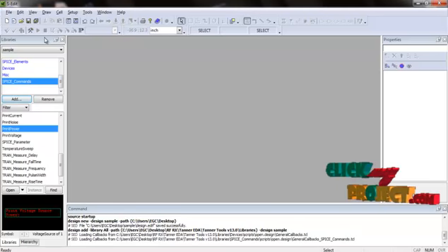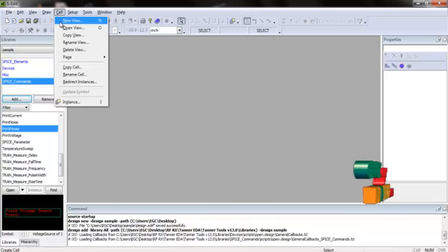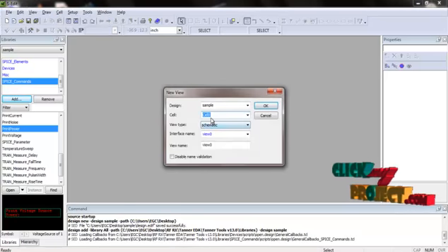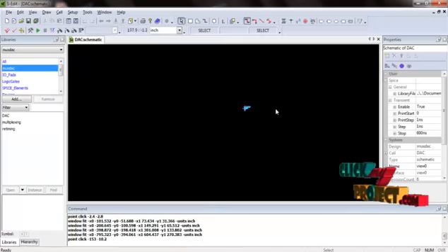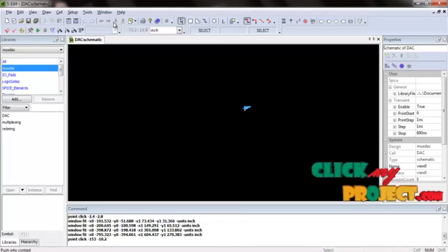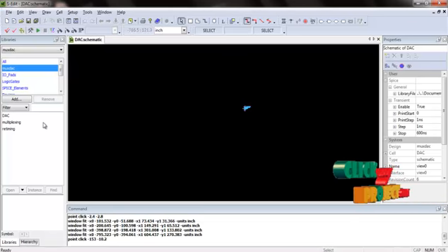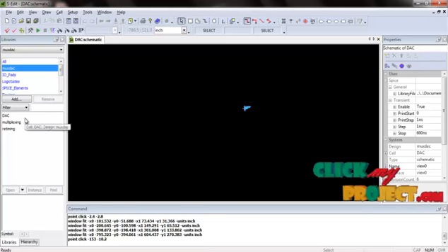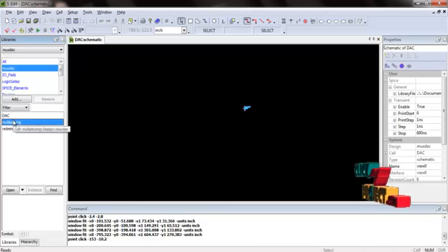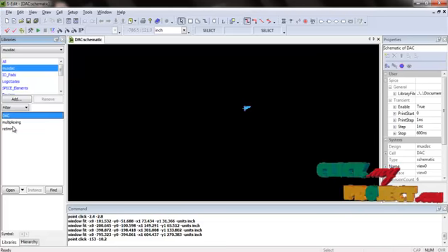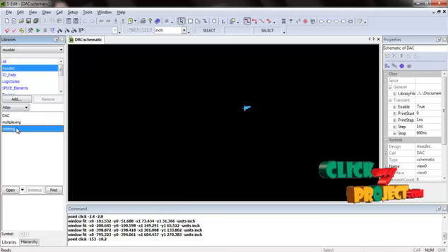After adding the library files, now start the simulation using the cell option to create a new view. Assign our cell name, and after assigning the cell name, click OK. In our product we are using 3 different cells to design it. They are retiming, multiplexing and digital to analog converter. The first block is retiming.